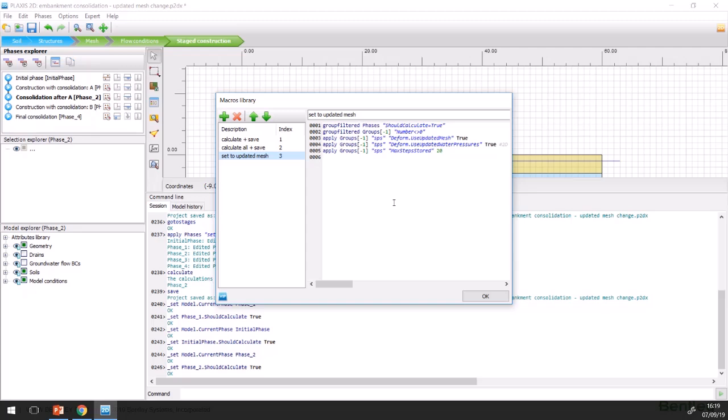But of course at the end that gives us 2 additional groups, and if we run this command several times, we get a lot of groups in the model, which of course we don't want to have because these are just temporary groups. So what I will do, if I use these temporary groups, I'm just going to ungroup groups -1, and I'll do this again for the second time. So with that we can sort of ungroup this. I'll comment them out so you can see why we would need to add these ones.